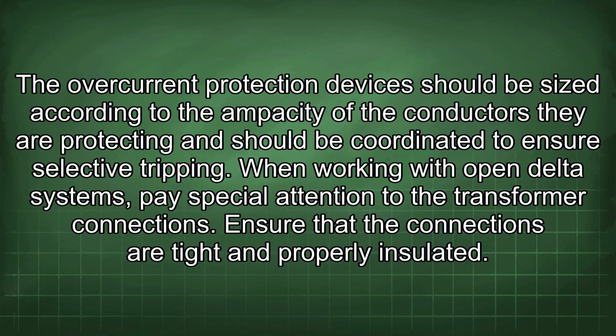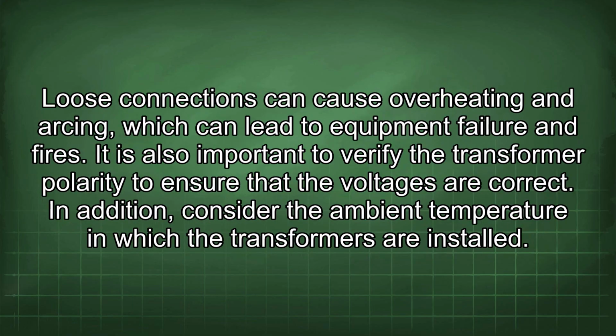When working with open delta systems, pay special attention to the transformer connections. Ensure that the connections are tight and properly insulated. Loose connections can cause overheating and arcing, which can lead to equipment failure and fires. It is also important to verify the transformer polarity to ensure that the voltages are correct.